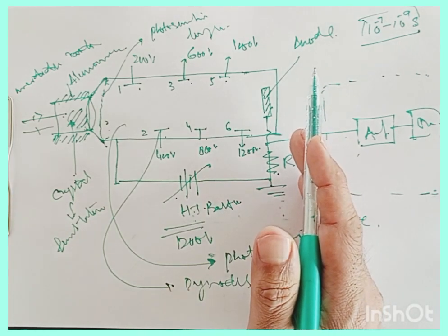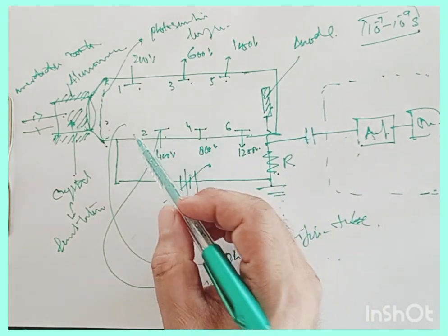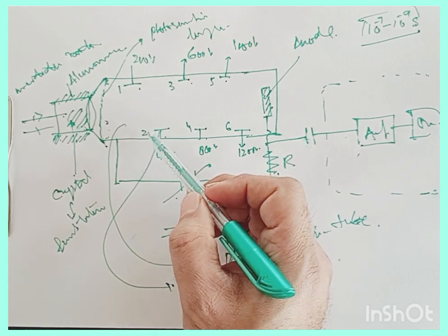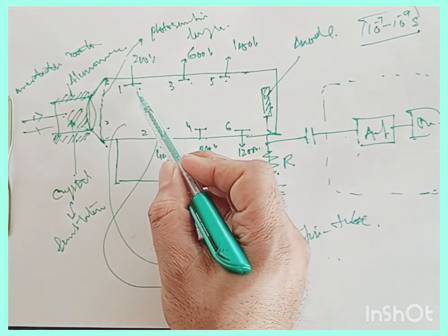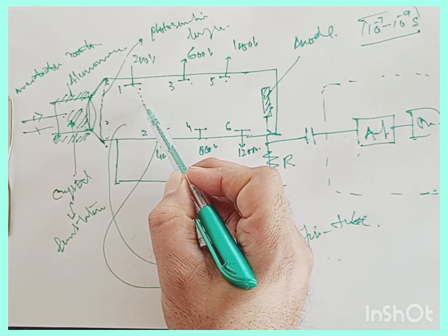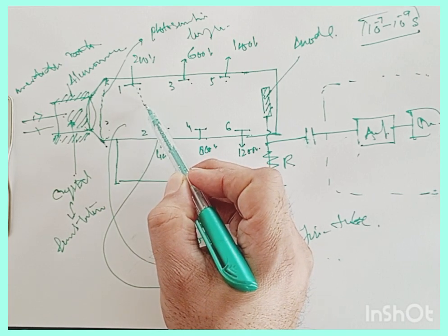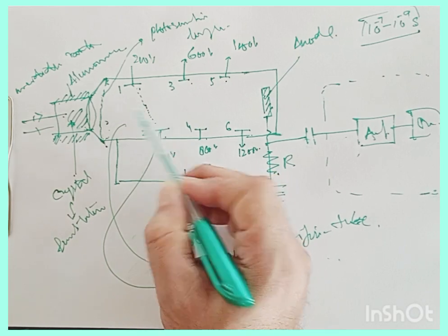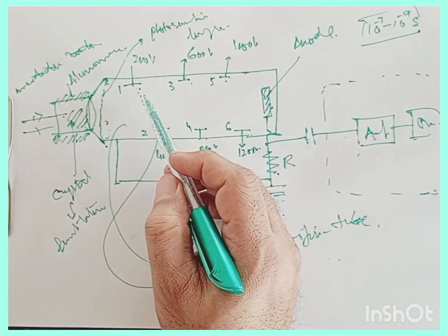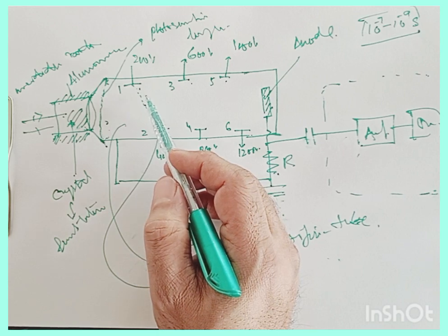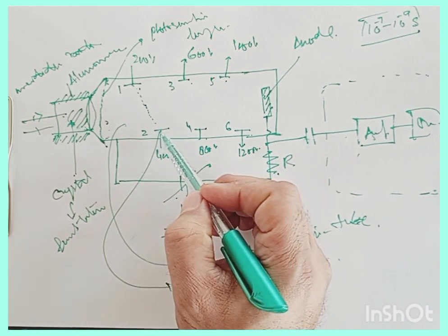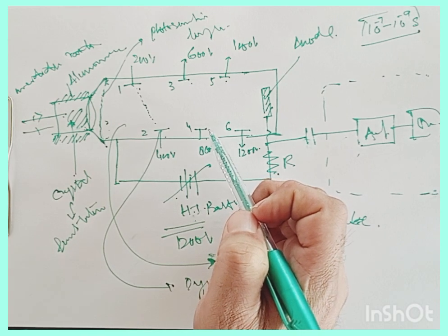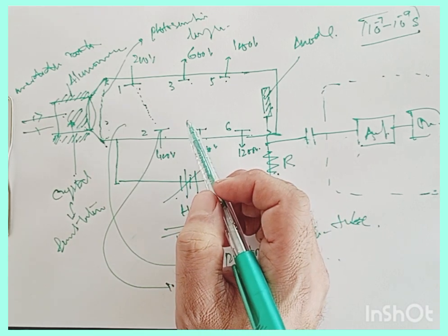And the photoelectrons are pulled to dynode 1, where they generate secondary electrons. They are emitted from the primary electrons that have fallen onto those plates. Now these in turn are pulled to dynodes 2, 3, and so on in succession, with several electrons emitted for each primary photoelectron.